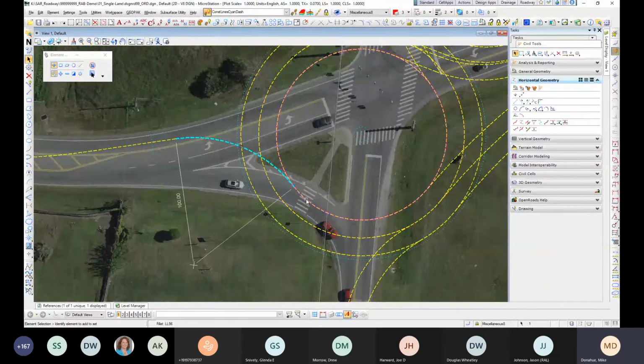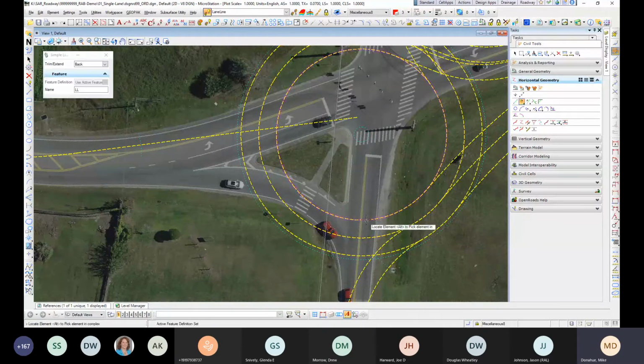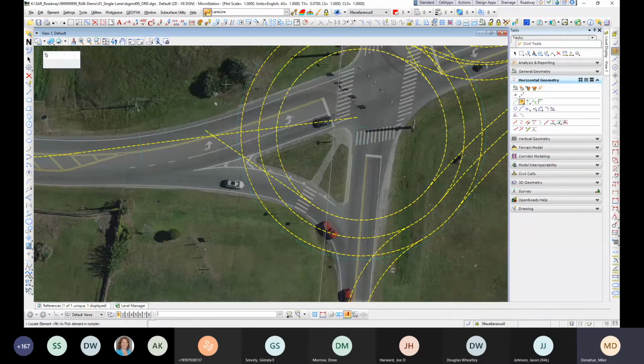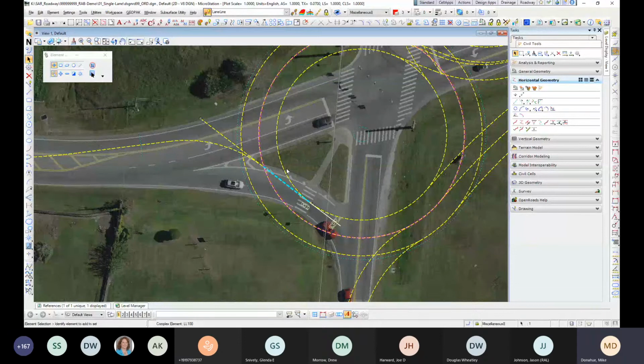And I actually went directly into this, so that's a mistake. So I'm going to back out and just delete that radius, and it'll return this element back to its full parent. So I want to come off tangent to this line. Oops. Let me change my feature back. No trimming. I'm going to add an arc at 100 feet now. Now trim both. So I know I have length here, but I'm going to want to tighten this up probably a little bit. I kind of try and target that second lane for the end of this guy.